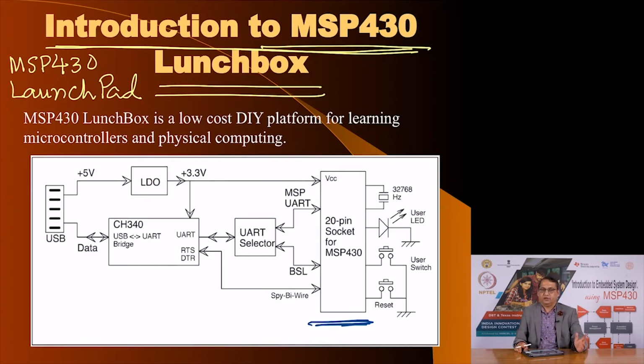Now I have been mentioning this several times in the past, that there are several ways of programming the MSP430 microcontroller. One is through the Spy-Bi-Wire method, which incidentally is the method that the official Texas Instruments MSP430 Launchpad uses. The other method is by accessing the JTAG interface pins, 4 of them, TDI, TDO, TMS and TCK.